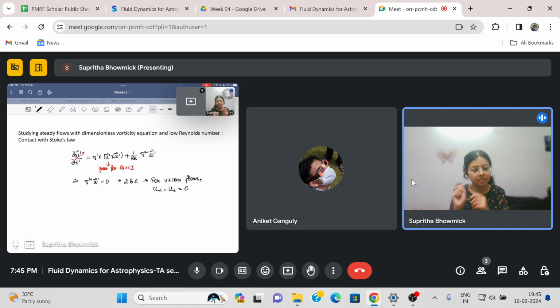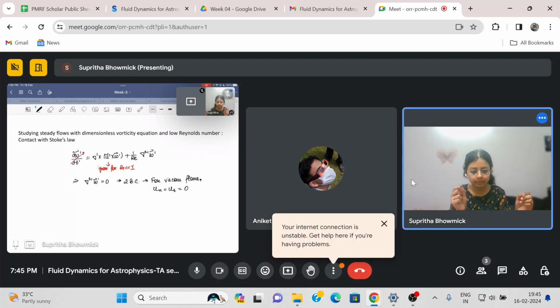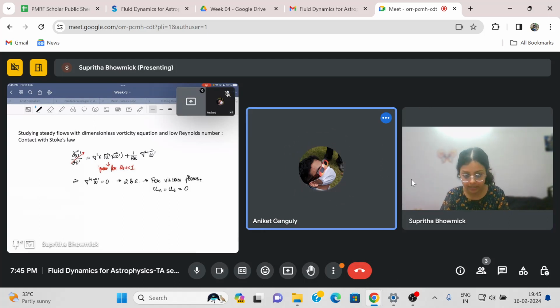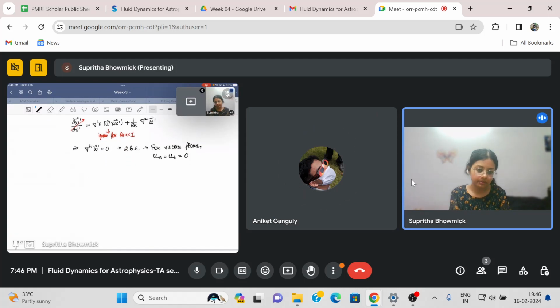You see how it varies. You measure the drag force by taking various Reynolds numbers, by tweaking the parameters of the system such that you're considering various Reynolds numbers. And then you measure the drag force, and you plot the drag coefficient with respect to the Reynolds number. You will see that for very high Reynolds numbers you have various different features of CD, the drag coefficient.